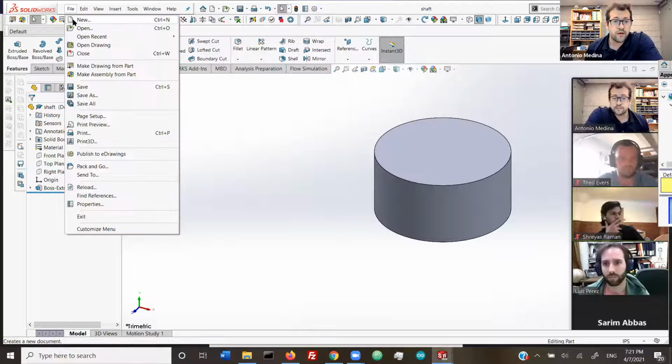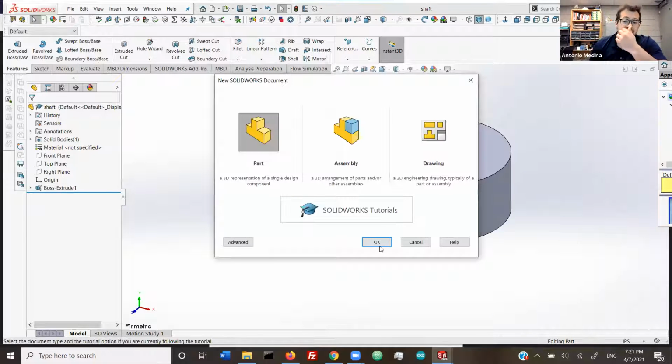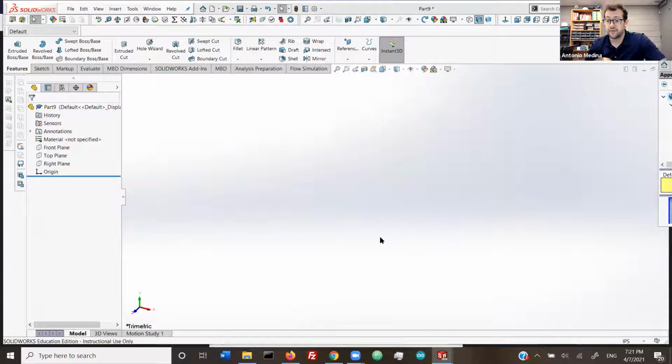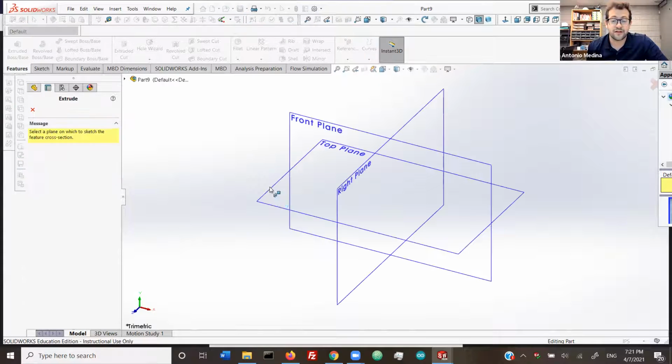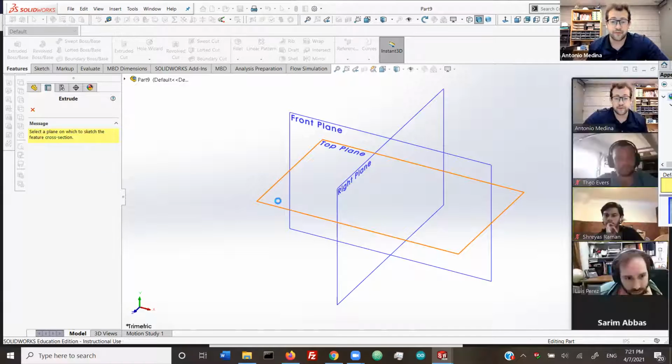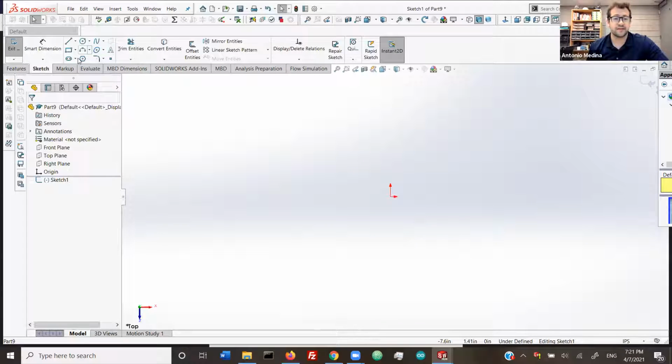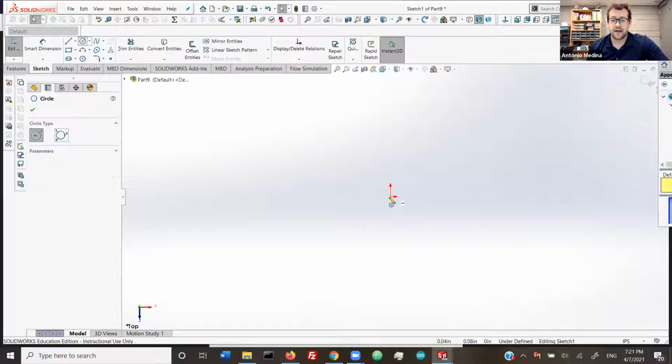We'll make another new one. And what we're going to illustrate next is how to add motion as if you were running a motor from something. You can hopefully start to imagine that this can be very helpful if you're designing robotic systems. So now let's design the thing that's going to go around the shaft, so like the actual spinning, either the head of the servo or the motor or whatever. So let's do a top plane. Let's design around the shaft that we just created.